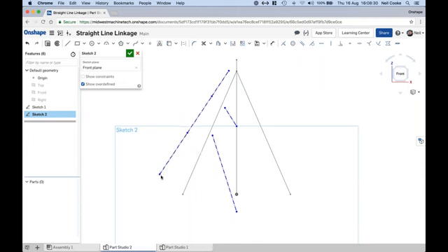And then just to position it and get the length right, I'm going to use the coincident constraint to make this attached to here, and then I'll attach these two to here. Okay, so we're getting something here now. So we're getting these two connected, and they have a pivot location relative to the center of the mechanism. The next thing I want to do is, because it's symmetrical, I won't bother doing the right-hand side, but we do want to do the vertical position.